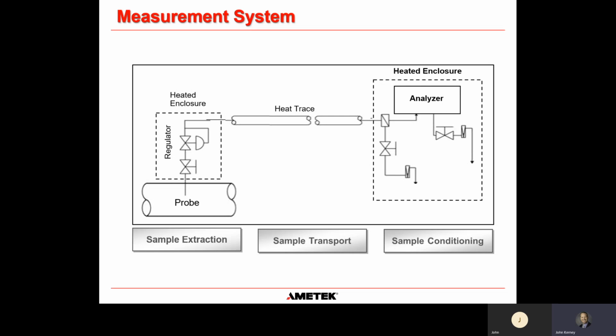If you're just measuring moisture content, then you could potentially just slightly crack the inlet valve, but fully open the outlet valve and run the system closer to atmospheric pressure, and you're measuring moisture content. And as we said in the example earlier, if pressure changes, moisture content doesn't change because we haven't added or subtracted any water molecules to the device itself.